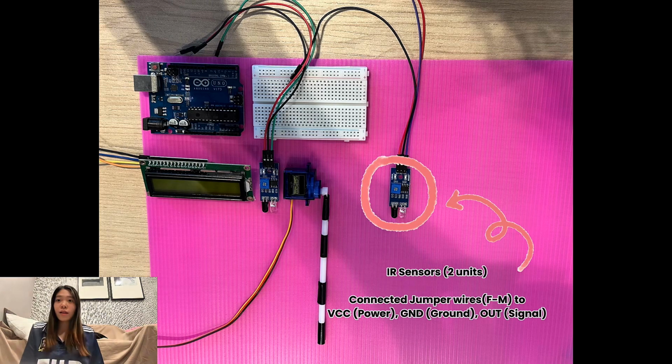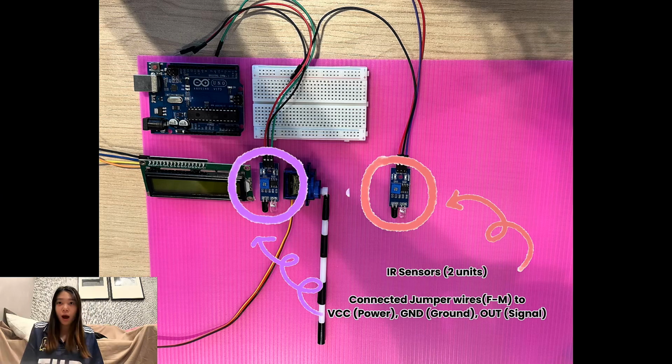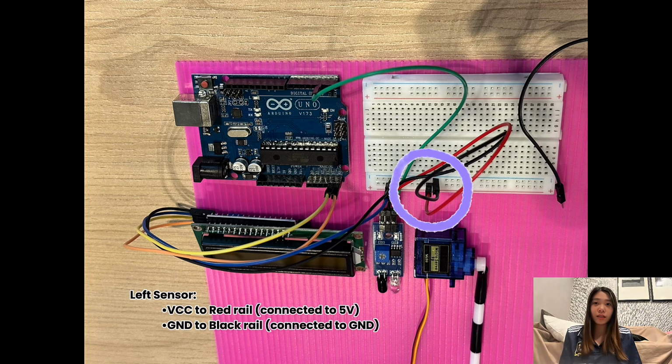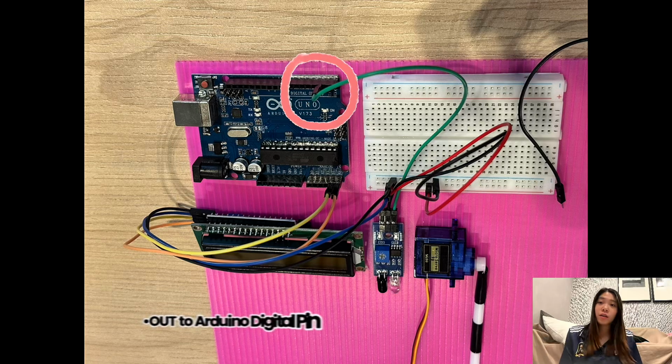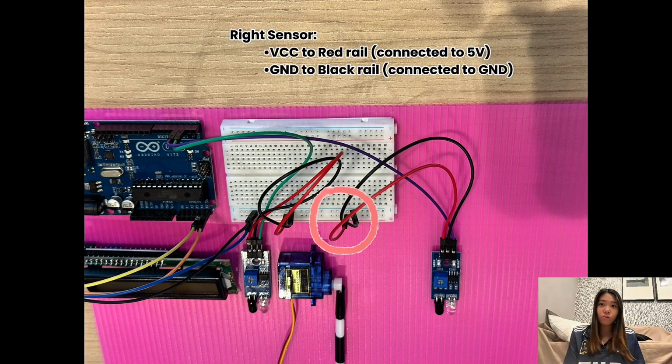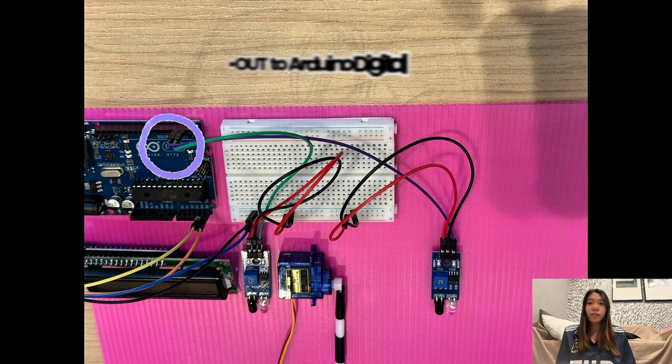Next are the IR sensors, of which we have 2 units. For both, we first connected jumper wires female to male to VCC, ground, and out, which is the signal. For the left sensor, VCC and ground are connected to 5V and ground on the breadboard, and out is connected to Arduino digital pin 2. For the right sensor, we also connect VCC and ground to the 5V and ground on the breadboard, and out is connected to Arduino digital pin 4.